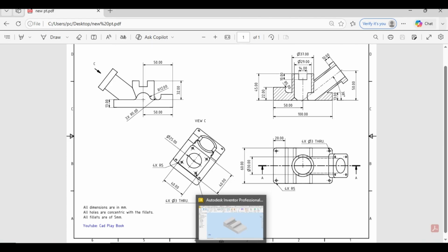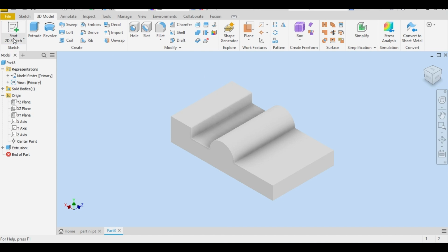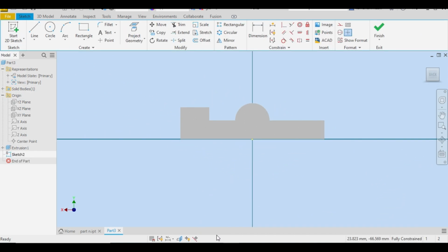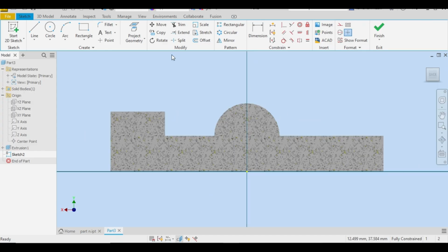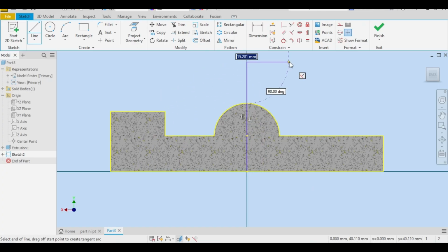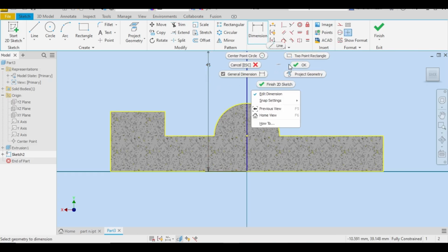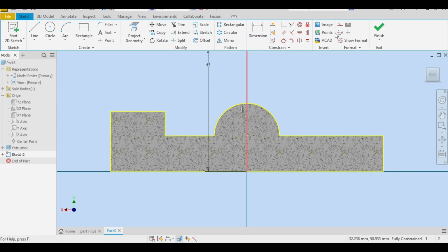Now let's start creating a sketch in the middle like this. XY plane, slice graphics or press F7, select the geometry like this. Now we'll add a center line, so we can draw a sketch and use the revolve feature here. 45 millimeter is the height for this line. Let me select this line and turn it into construction.